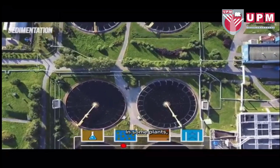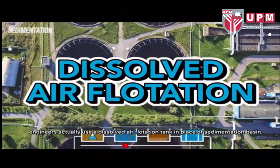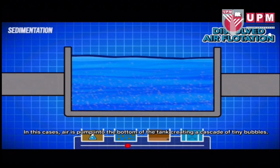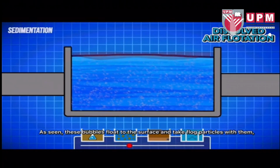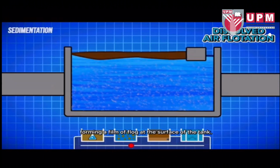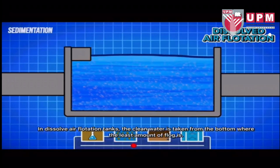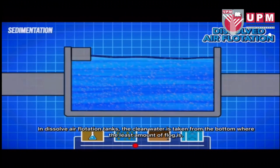In some plants, engineers actually use a dissolved air flotation tank in place of a sedimentation basin. In these cases, air is pumped into the bottom of the tank, creating a cascade of tiny bubbles. As seen, these bubbles float to the surface and take flock particles with them, forming a film of flock at the surface of the tank. Then, a sweeper arm pushes the flock into the collection basin where it is taken to a handling facility. In dissolved air flotation tanks, the clean water is taken from the bottom where the least amount of flock is.